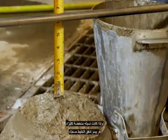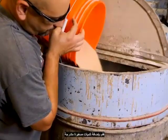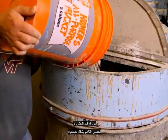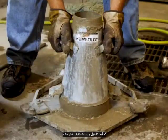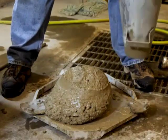If it is too low, or the mix appears harsh and does not flow properly, gradually add small measured quantities of fine or coarse aggregate as appropriate. Then thoroughly remix and retest the concrete until the desired slump and consistency are achieved.